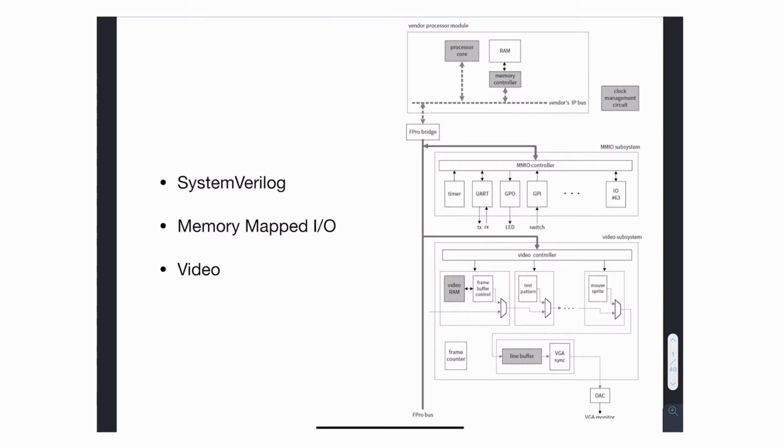Okay, some of these will involve accelerometers, some of them will involve SPI or I2C communication protocols and so forth. We'll be designing the hardware, writing the SystemVerilog for it, designing a driver to communicate with the microcontroller, and letting the microcontroller program, which is written in C, control all of this and do something useful.